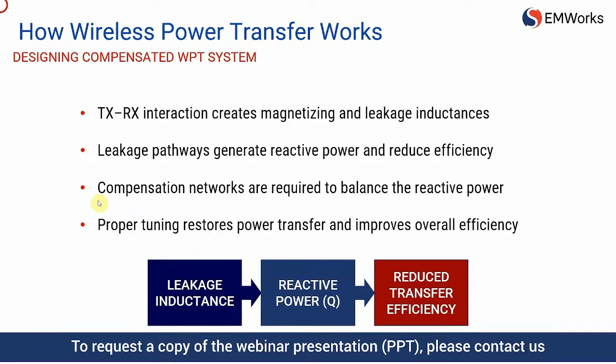To solve this problem, a compensation circuit is added to the system. By using capacitors arranged in series or parallel, the circuit is tuned to resonance, which cancels the reactive power, improves the power factor, and significantly increases the overall transfer efficiency.